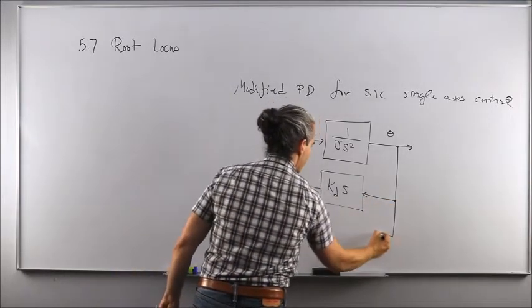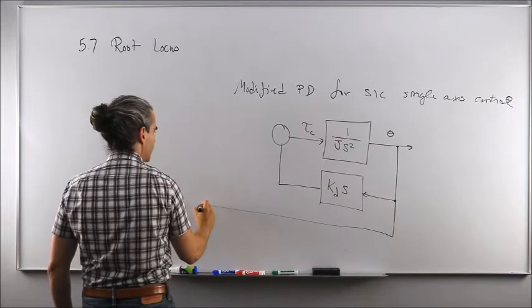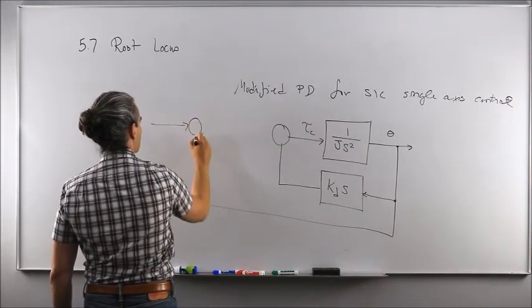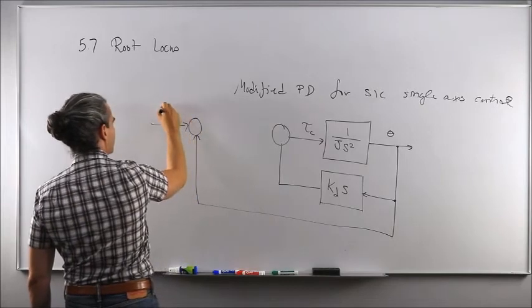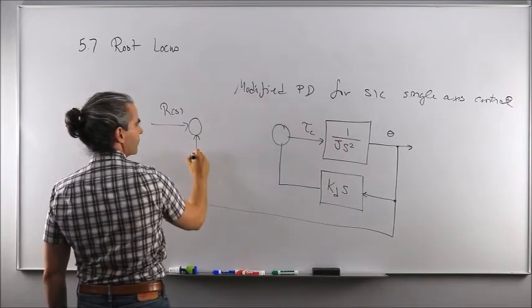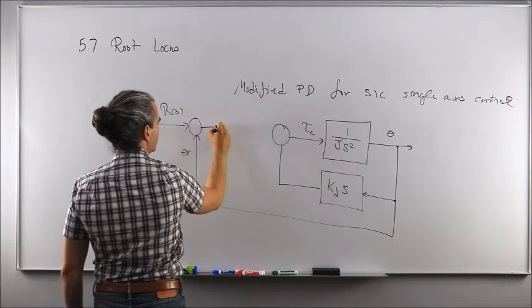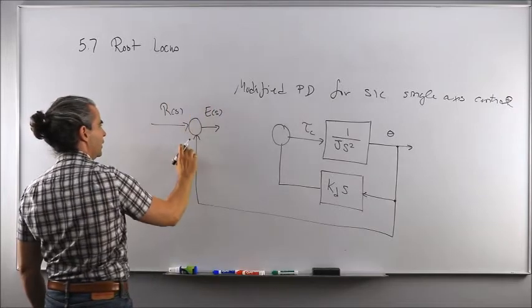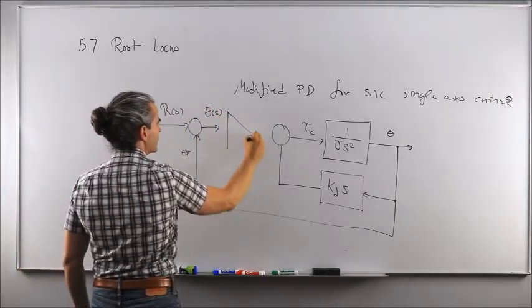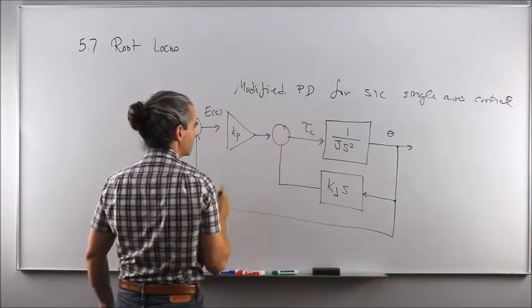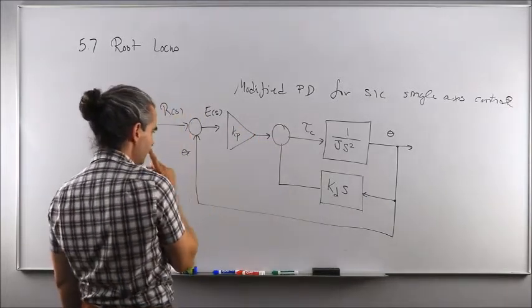We also feed back the current angle of the spacecraft and compare this with what the user wants in terms of reference signal, R(s), minus the current angle to produce the error signal between the desired angle and the actual one. And this is being multiplied with the proportional gain Kp.